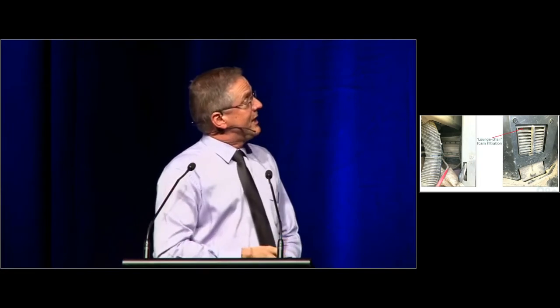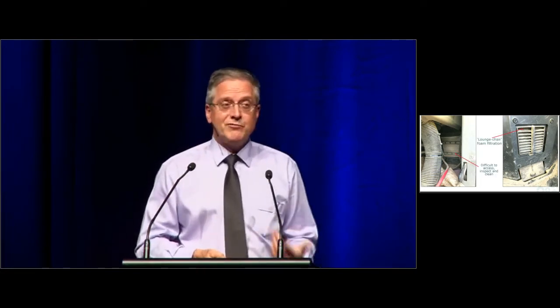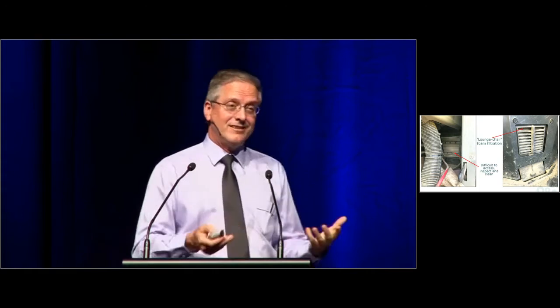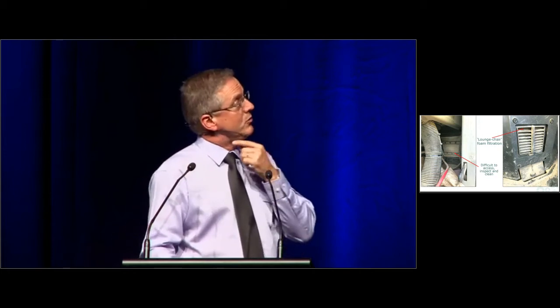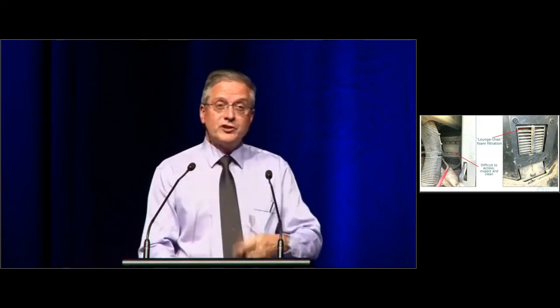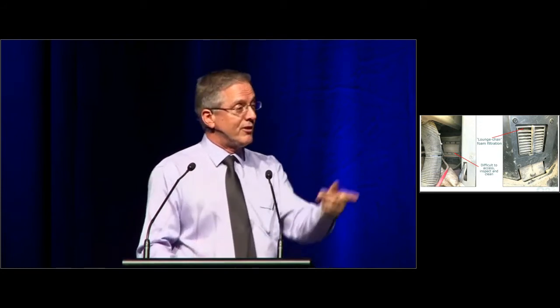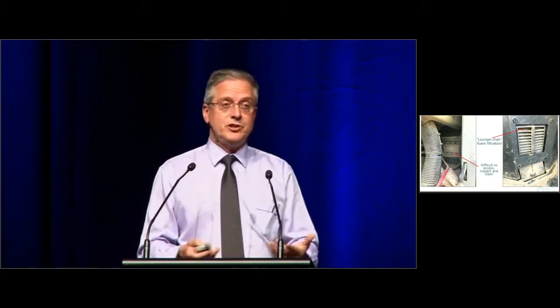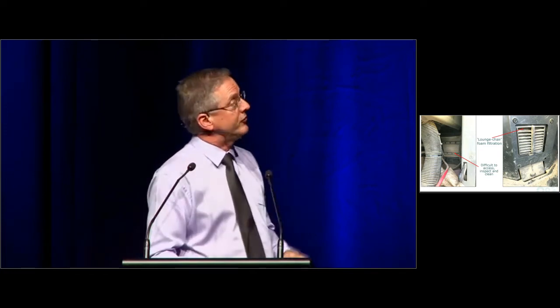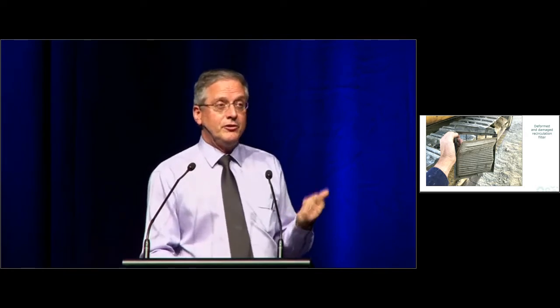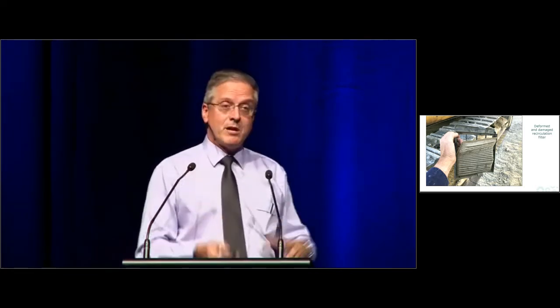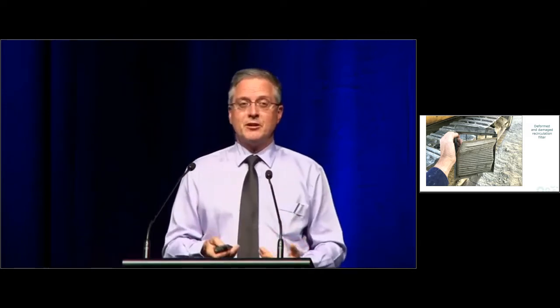These are some examples of cabin air conditioning filtration and the ineffectiveness of some in-cabin filtration. So some of the pre-filters or the recirculation filters are just made of the kind of foam you dig out of the chair you're sitting on, which is entirely ineffective at trapping respirable dust. Filters difficult to access, deformed or damaged filters. This is a recirc filter in the frame. The plastic frame was cracked and busted. The filter wasn't sitting properly. All this contributes to a recirculation of dangerous particulate matter within the cabin.